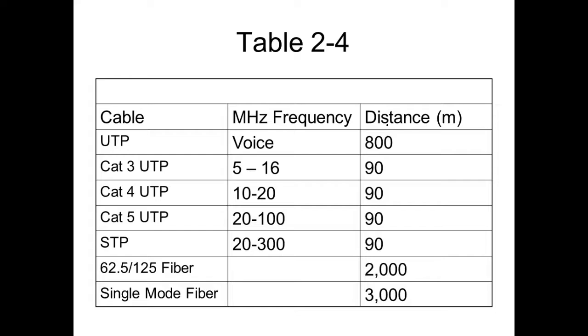Well, no, what happens at 90 meters is it's not the impedance, it's the R of the wire. You've only got a certain allowable dB drop over that length, and if you get past that dB, then there's no guarantee that the receiver is going to receive the data. The impedance of the cable doesn't change because of that, which is so dang cool. So I can have an RG59, it's 50 ohm whether I have 8 feet or whether I have 100 feet at 100 megahertz. But the R is what gets us, right?